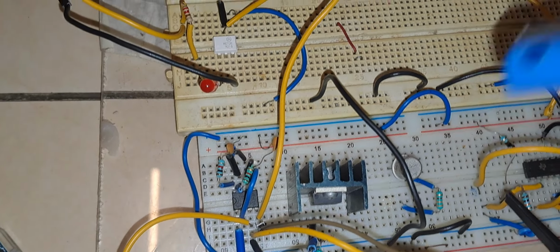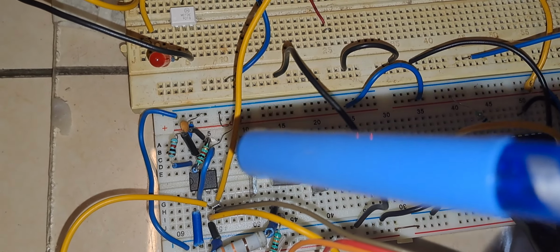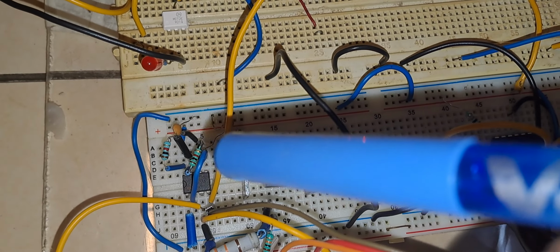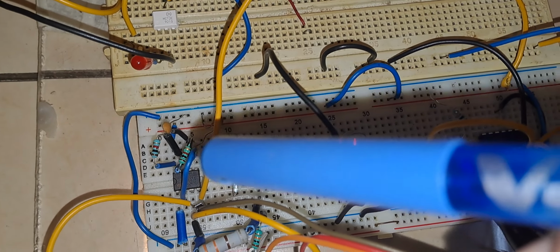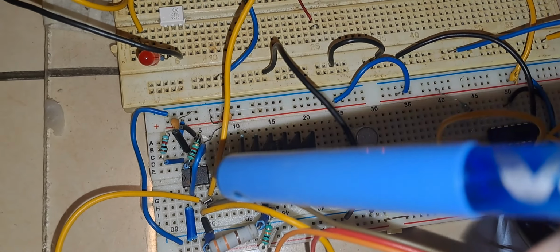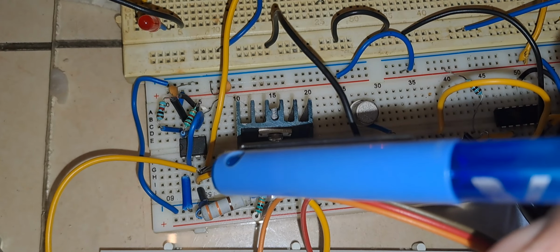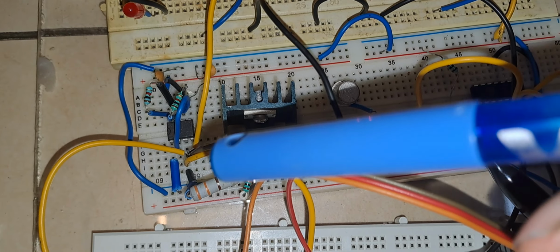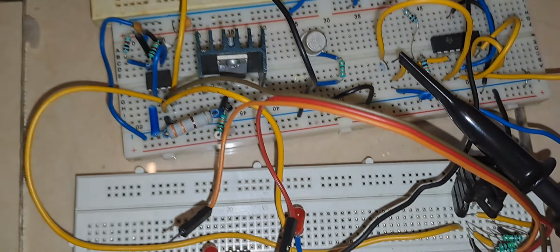So as you can see, the 555 timer IC is wired in astable multivibrator mode. So it is designed to deliver a frequency of 48 kilohertz. So from pin number 3 of the 555 timer IC, we are going to get a 48 kilohertz mixed data signal. So from pin number 3 we will be getting the final modulated signal, and this signal I am feeding to the